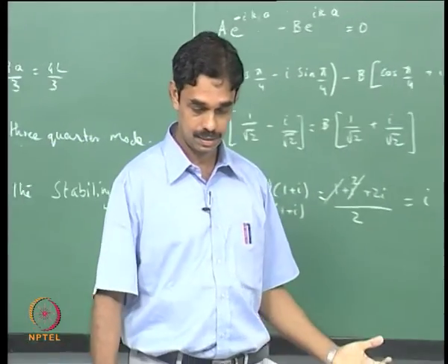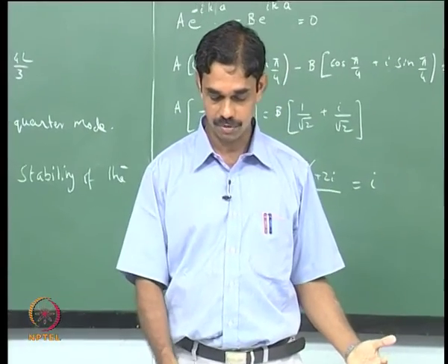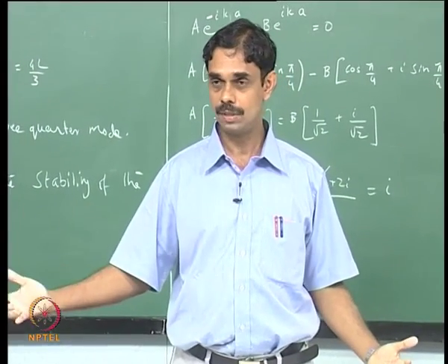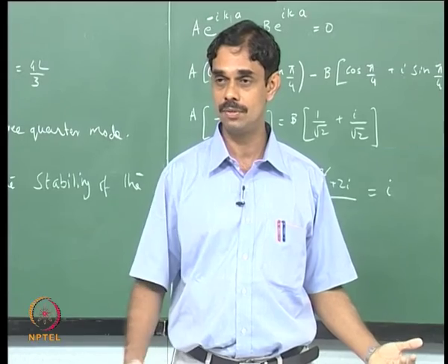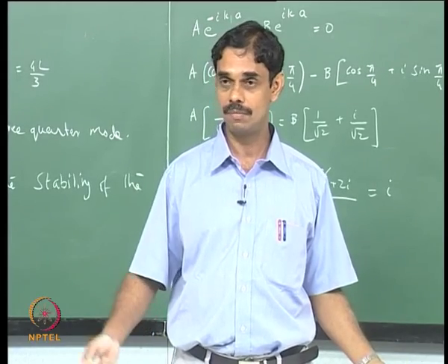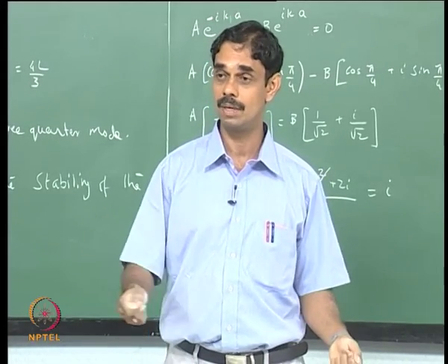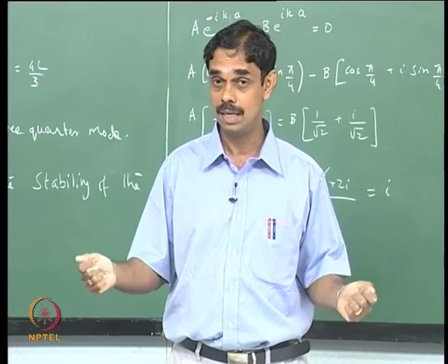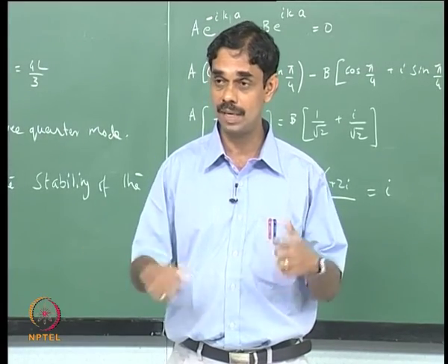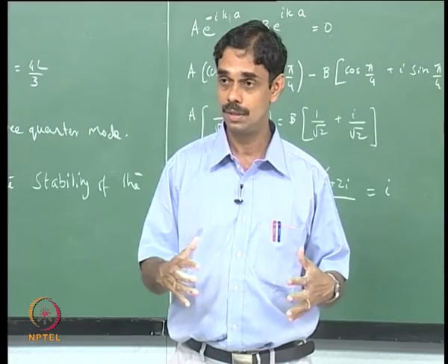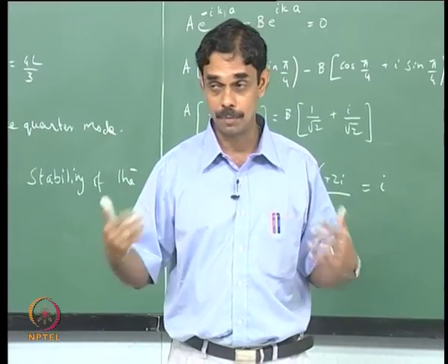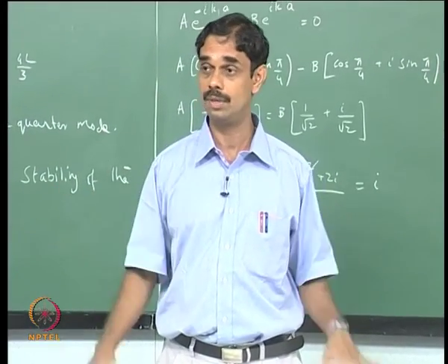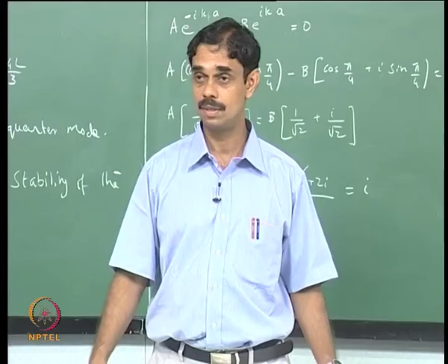We will look at that in the next class. But what it involves is, we have to put some loudspeaker, and what phase should you put, we do not know, right? So we have to measure the acoustic field using a microphone, whatever is the acoustic pressure at some place, and then you have to find the appropriate phase, or the appropriate boundary condition you have to put, so that the acoustic field dies down. So this is the principle for active control.